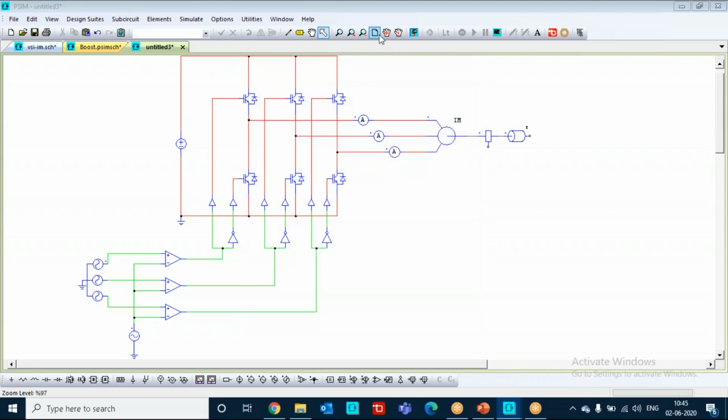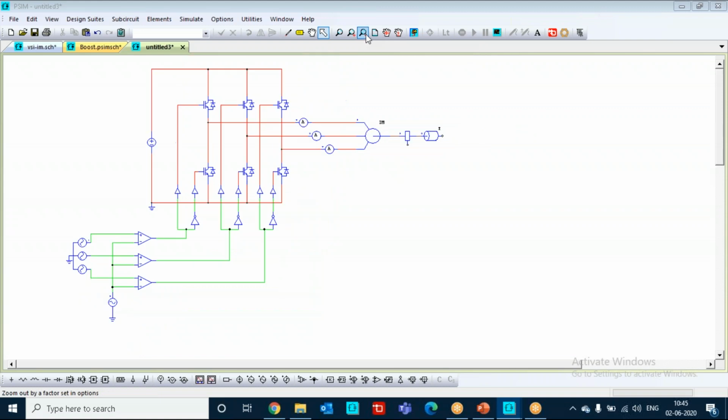So we have built the circuit. I hope everyone completed the circuit, right? Now you can take this voltage probe. That probe you can keep to see the speed at the speed sensor. Here on the down part, in the commonly used blocks, you can get the voltage probe. You can keep that voltage probe at the speed sensor by rotating.